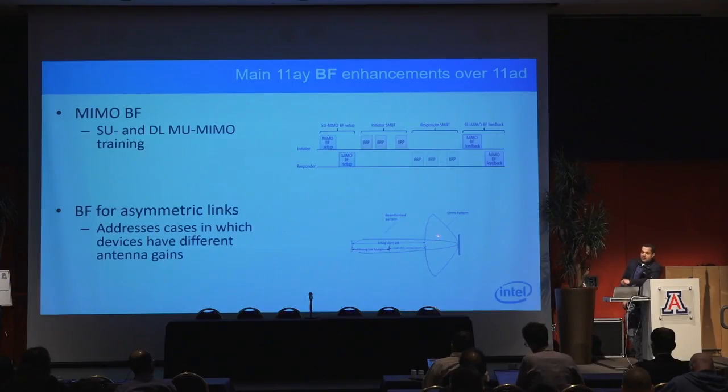This could actually be quite a common scenario, where the access point is just listening, but it doesn't have any gain because it's trying to listen to a lot of stations, but the station cannot really reach the access point. However, if the access point were pointed towards the station, they could actually communicate with each other.